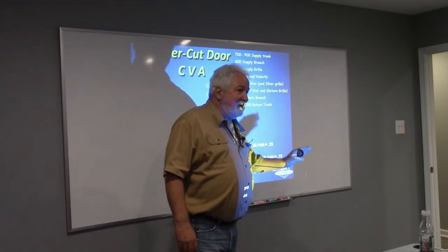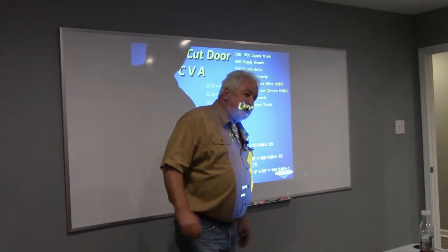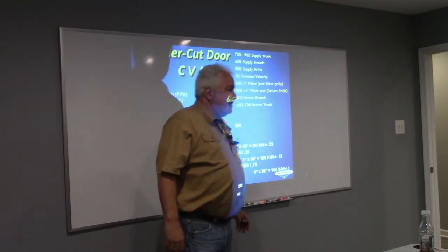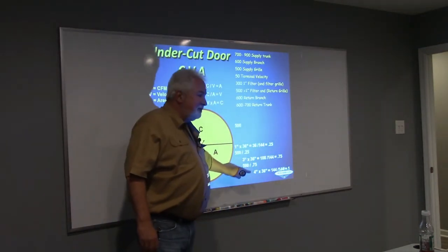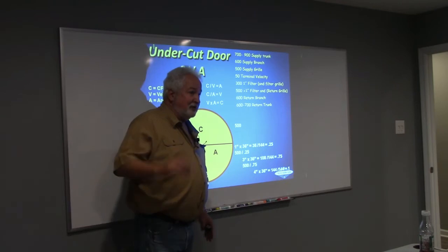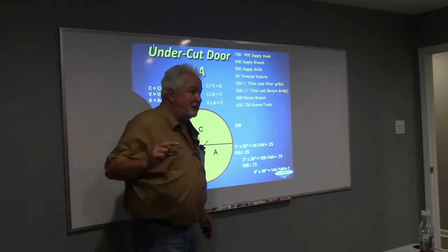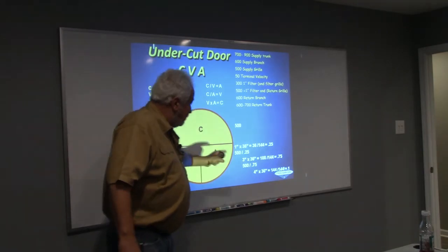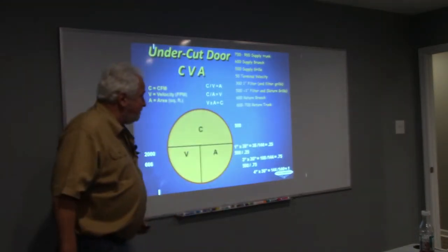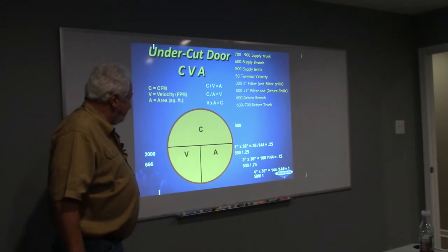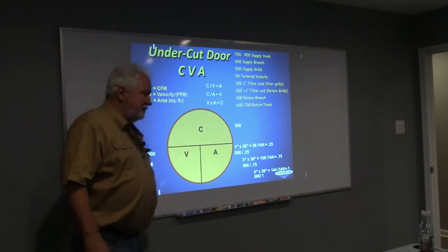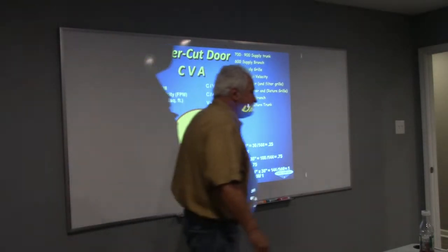You don't have to worry about privacy because the kids are going, hey, what y'all doing? We're talking 4 inches off the bottom of that door, and that's a woman's 4 inches, not a man's 4 inches, all right? So 4 times 36 is 144, divided by 144 is 1 square foot, divided by 500. Now that air is moving under there at 500 feet per minute.